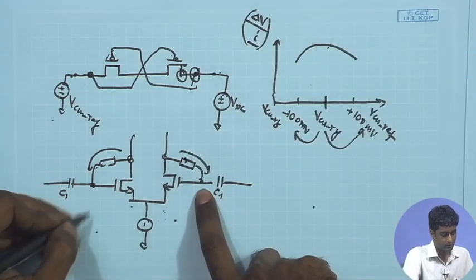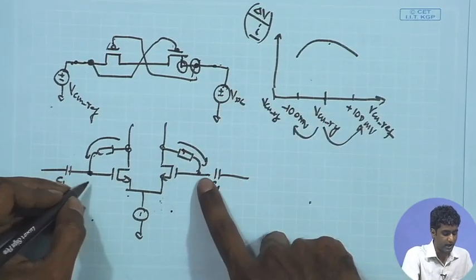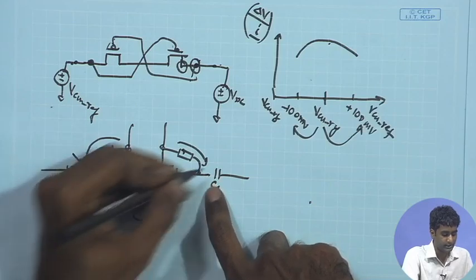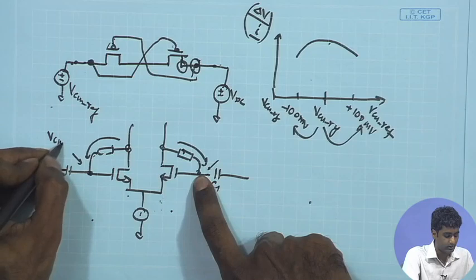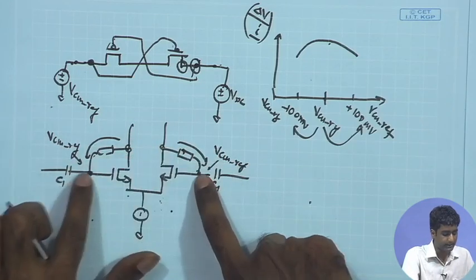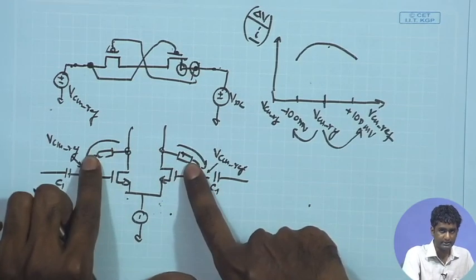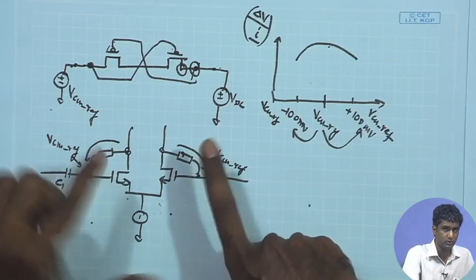So, one of the standard techniques to make it fast is to have some initial conditions. So, in the simulation, if you are putting some initial conditions, so that these two potentials are initialized to the value equal to VCM ref, in that case, you will not be dependent upon this resistor to set up this value equal to the VCM ref.